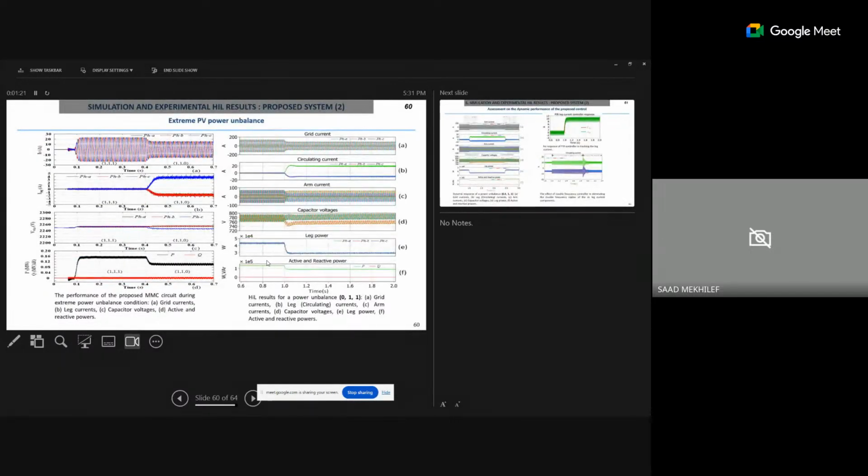That's very interesting. When you have this kind of modular converters connected together, you will have this problem of circulating current, especially if you have a wind farm. So this can also be used in wind farms, when you have two wind turbines with different wind profiles.